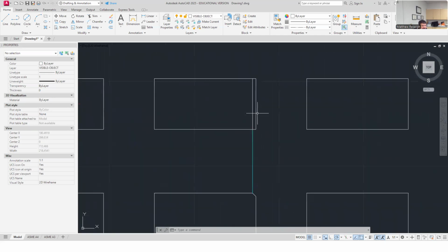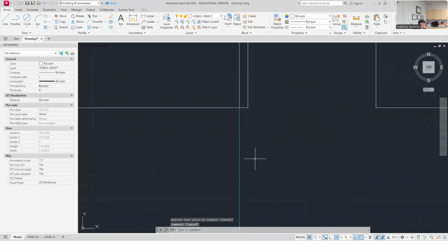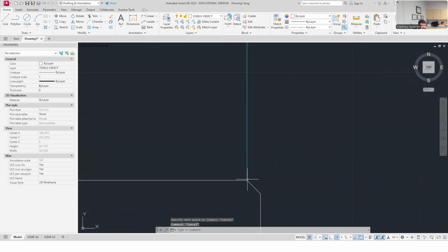So what we call that, which you've learned about in chapter 8, is foreshortened. That means that when I look down on top of this, when my eyes are perpendicular to this plane, when that bevel falls down and away from me, it is foreshortened, meaning that if I were to snap a dimension here, or even measure this, it is not the dimension of how long this is, right?